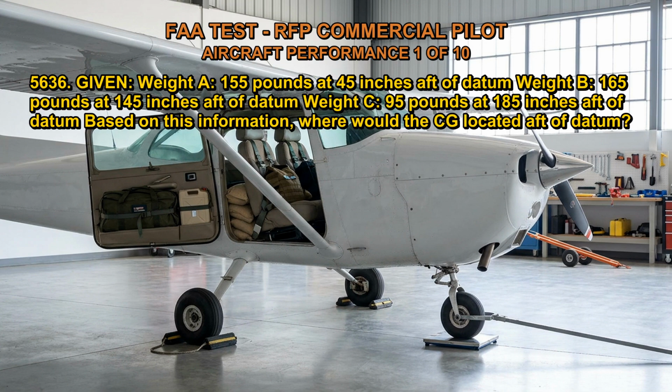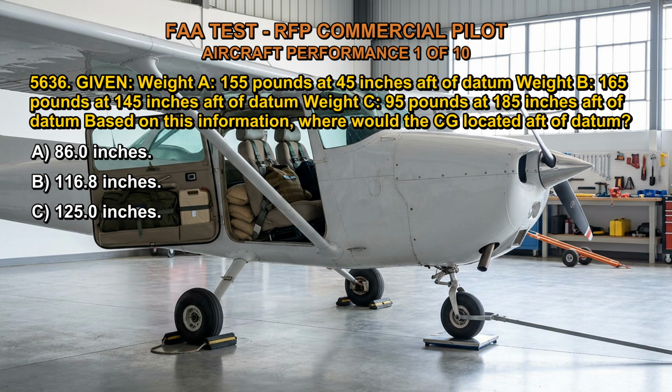5636. Given weight A, 155 pounds at 45 inches aft of datum; weight B, 165 pounds at 145 inches aft of datum; weight C, 95 pounds at 185 inches aft of datum. Based on this information, where would the CG be located aft of datum? A. 86.0 inches. B. 116.8 inches. C. 125.0 inches.